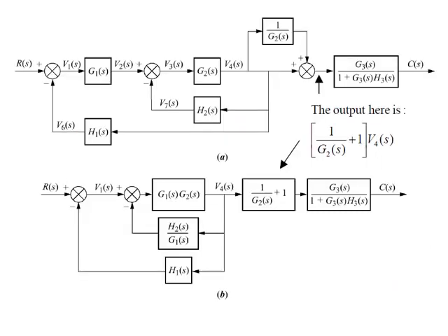So notice here, the block I just mentioned, G2. G2 was here at this location, and he moved it to this location. What is here? It's a pick-off point. This is the output of the pick-off point. Pick-off point output, we send it to the input. So the other output will take the reciprocal. So it takes 1 over G1.